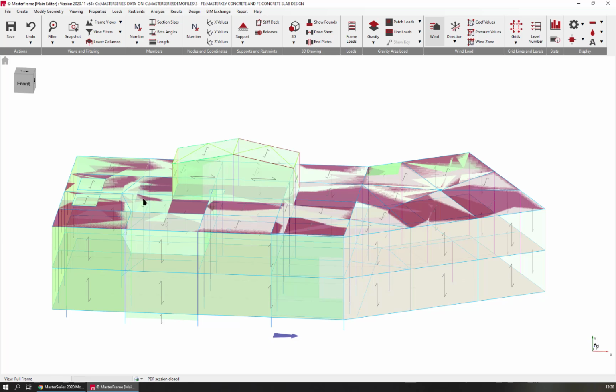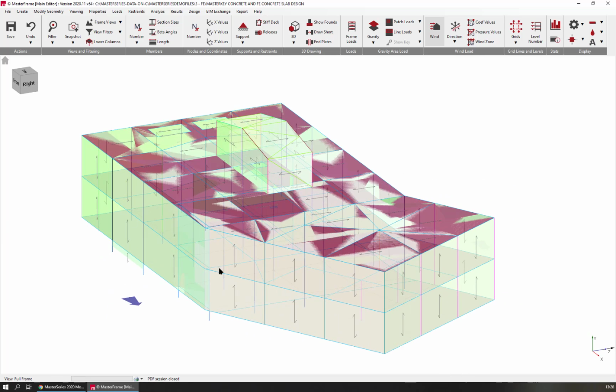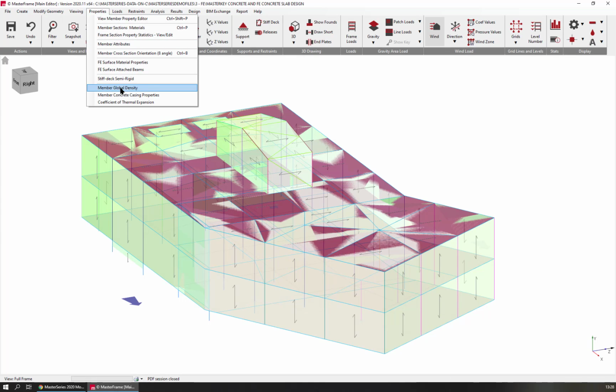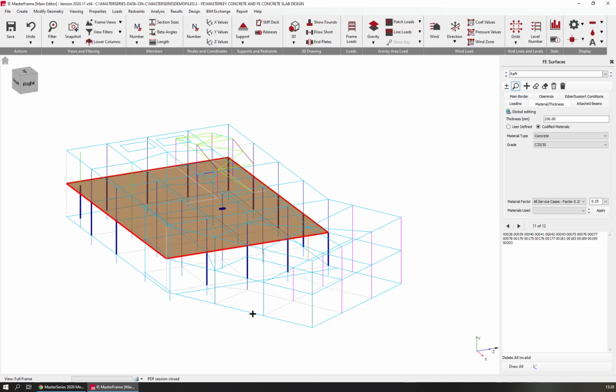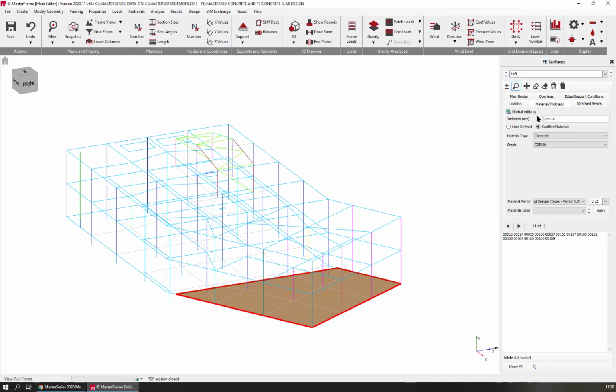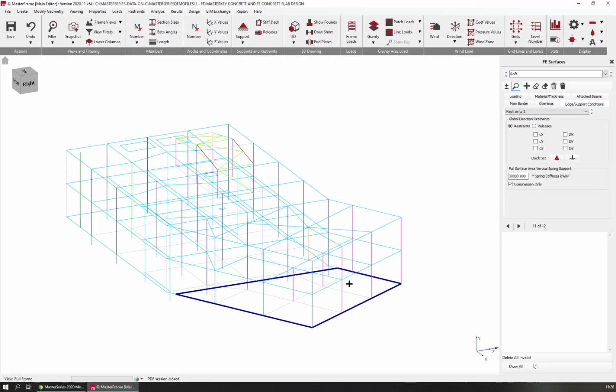The last thing actually was we didn't set our surface loading properties, surface materials. Looking at this here, we can see that we're codified, but if we look at the support here, we will see that we have a subgrade modulus of 30,000, so it's a stiff clay. It's still going to give us some problems, but 30,000 is a reasonably stiff clay.